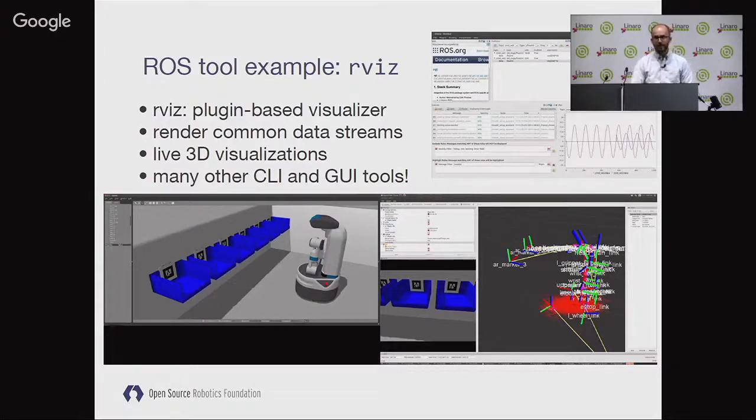The most common and perhaps most useful mode people use this in is actually a 3D representation of any data source in the ROS system. You can then plot it and visualize it and zoom in and zoom out and rotate as you need. A lot of robotics systems deal with spatial data, whether you're looking for objects in the world and you're wanting to plot the robot's hypotheses of where those objects are, or making maps of the world, or drawing path plans, or watching robots as they drive around. A lot of robotics software tends to be spatially oriented. And so being able to debug this in a live view with everything represented in the same spatial tree is a very useful thing.